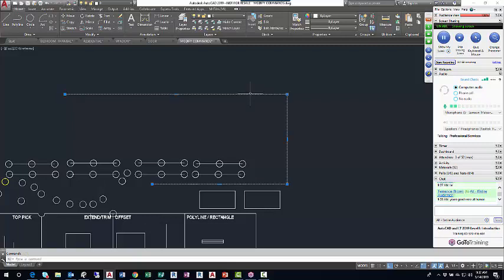because I would have to provide to the fire marshal a voltage drop calculation, which was a product of taking the length of your circuit and the number of devices on that circuit, and it would tell me how much voltage is being pulled in from the circuit.